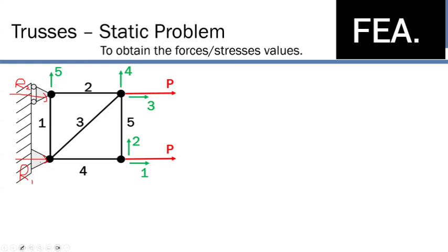So now we have these two unknowns. How many equations of motion do we need for two unknowns? 2, right? So the first one will just sum up the forces in x equals 0, and it's going to be R1 plus R2 minus 2P equals 0, right? Now that's not quite enough because we have two unknowns right here. Although obviously with the eye test we could pretty easily solve this problem, we're going to go through it kind of systematically so you understand the process.